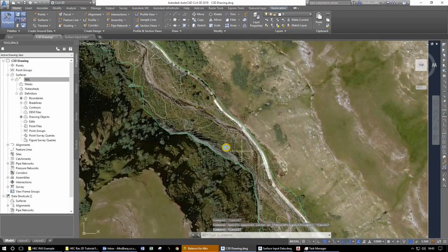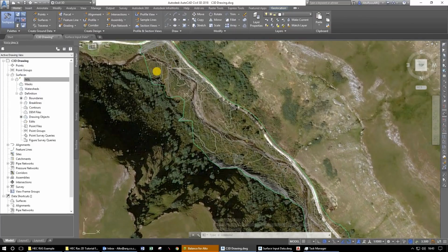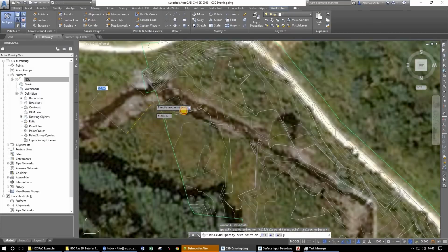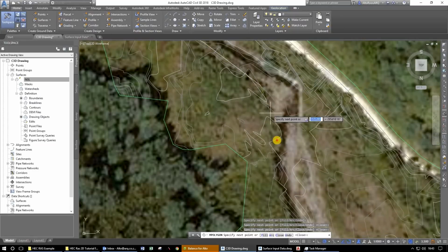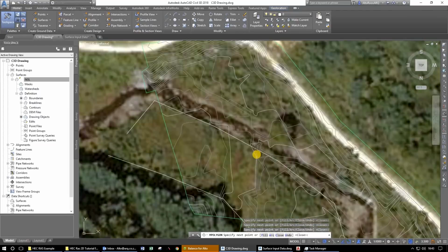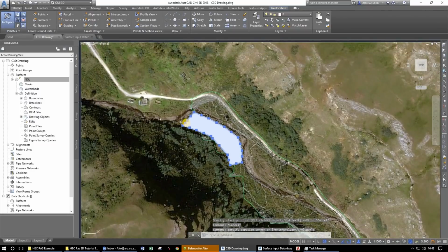Let's just create, as an example, the polygons as well. In my previous little segment I used polylines. Polygons is basically a similar type of thing. It's a polyline that you draw as a boundary of some sort, but the only difference is that after you've drawn it, it automatically hatches it for you, as you can see over there.